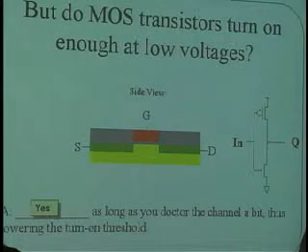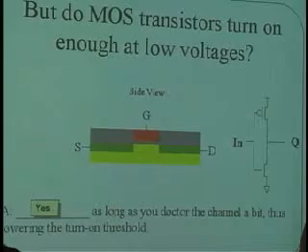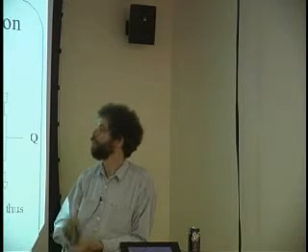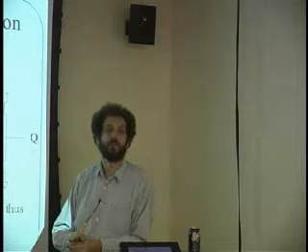Yeah. What happens if you're lowering it from like 5 volts to 2 volts? Wouldn't you have more metastability issues? Then how do you deal with that? So it's absolutely correct. Remember, we had VOL and VIL and VOH and VIH, and there was this idea of a noise margin, which was the difference between the voltages on the input and the voltages on the output. The lower the voltages for the whole chip, the harder it becomes, in fact, to maintain decent noise margins throughout the chip, and the easier it is for you to get into that forbidden zone in the middle.